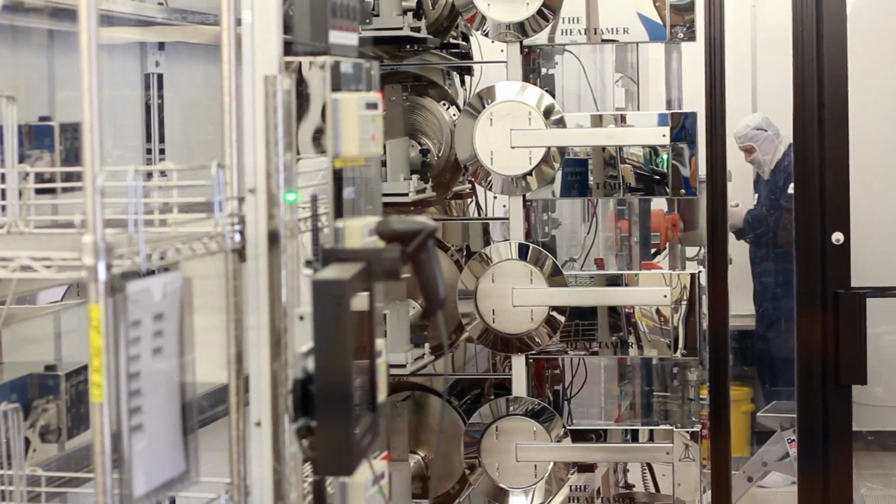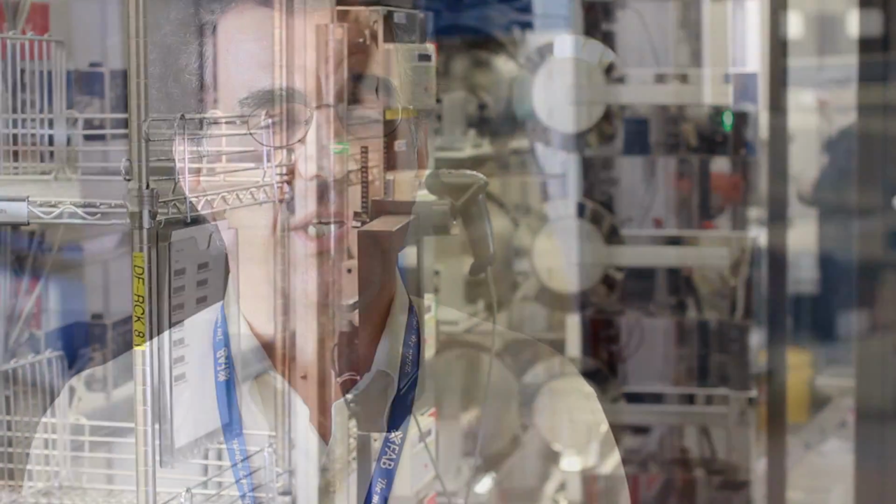Depending on the film chemistry, various gases are introduced in the plasma environment, and the films are etched in that area. Okay, this is our diffusion area. The diffusion area is a very high temperature processing, where the wafers see temperatures ranging from 400 degrees C all the way up to 1100 degrees C. In the process, the dopants are driven into the silicon, forming the junction of a transistor or a diode, or a film is grown at the high temperature.